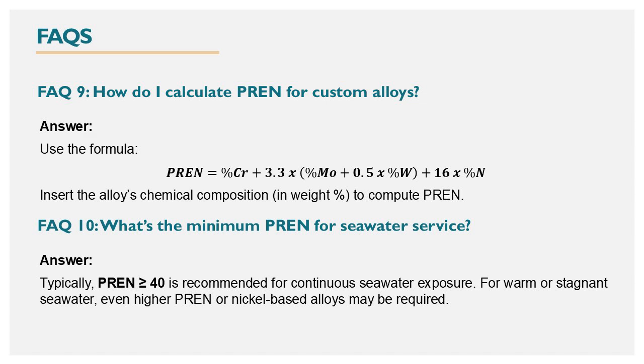Question number 10. What's the minimum PREN for seawater service? The answer is, typically, PREN greater than or equal to 40 is recommended for continuous seawater exposure. For warm or stagnant seawater, even higher PREN or nickel-based alloys may be required.